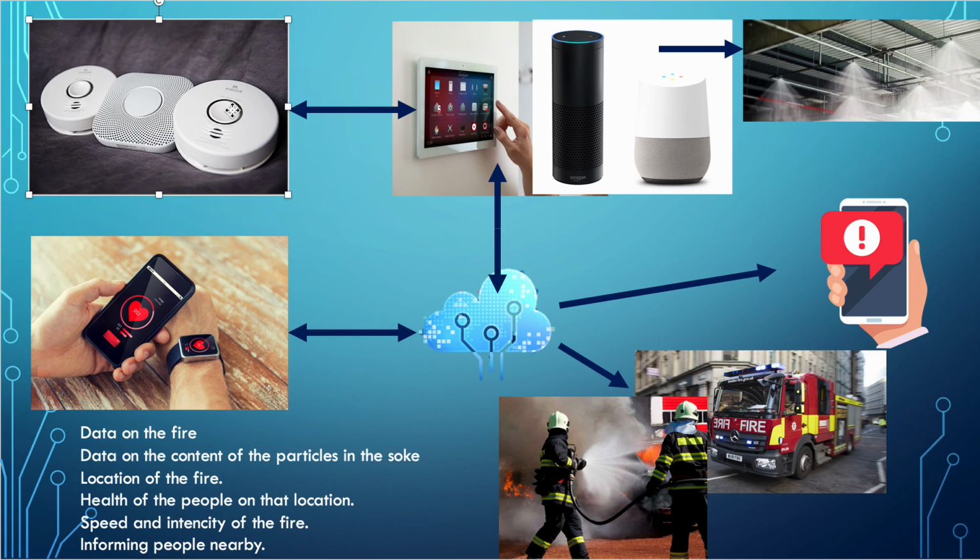the first thing that will happen is it will direct the data taken from the sensors into the control or the processing unit. That processing unit or the control unit will process that particular data, right? And first it will send that data to two places, one into the cloud or into the internet, and the other, it will activate the fire suppression system inside the building, right?